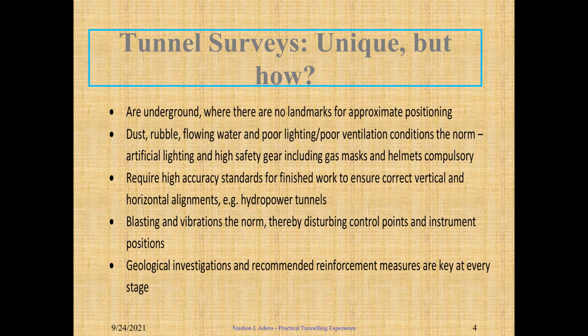So there was the necessity of having what we call adits. These adits are intermediate entry points into the tunnel that allow surveyors to go outside the tunnel and strategically tie the control points underground to the surface by running a traverse, and ensure that you are still within the designed mathematical framework for aligning this tunnel.